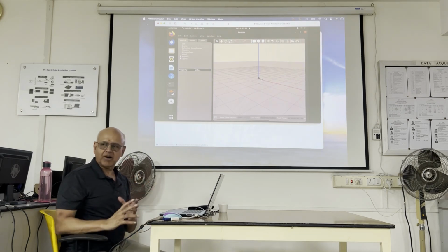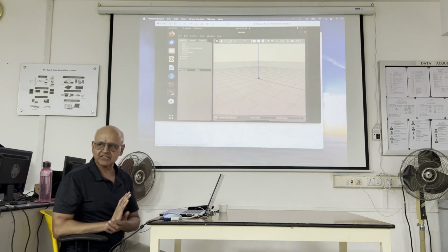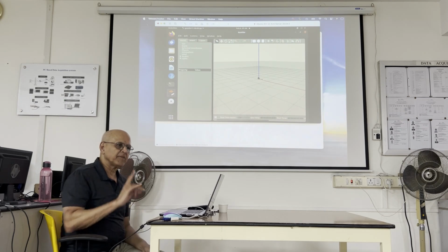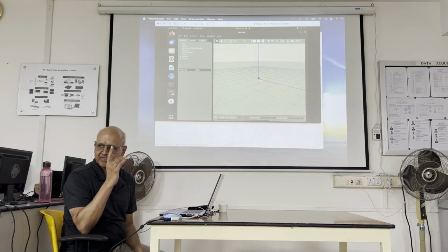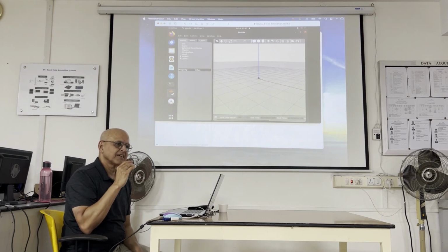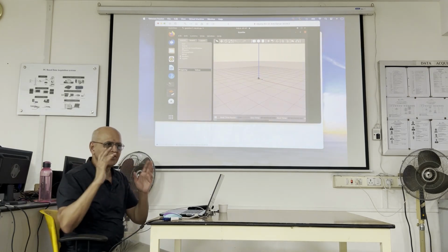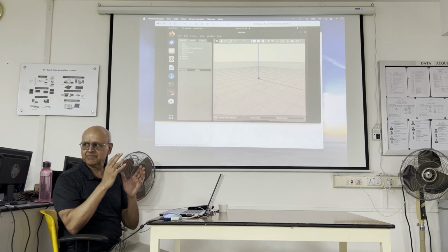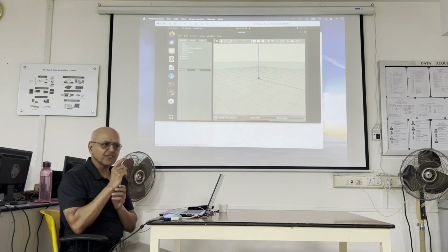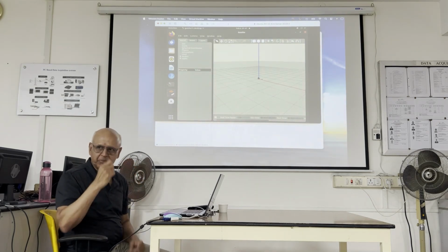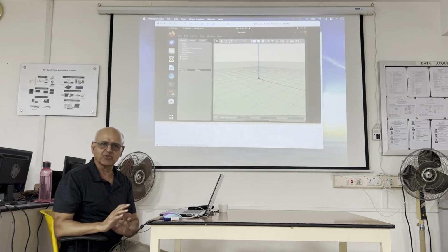Anytime you work with a robot, right, you have to define a world axis. And there can be only one world axis. So you cannot have a world axis here and then another world axis in Chennai. If you have a single robot, then you can have only one world axis. So that world axis is fixed. It's like somebody planted something in the ground. It's not movable.